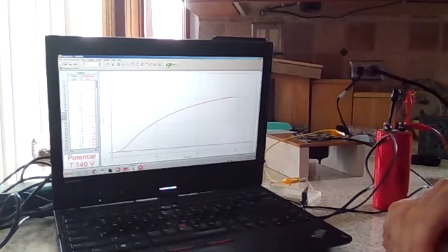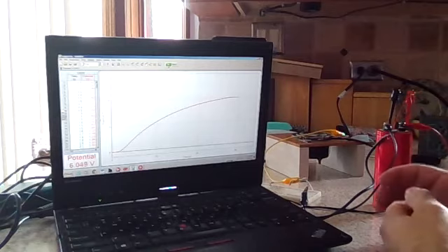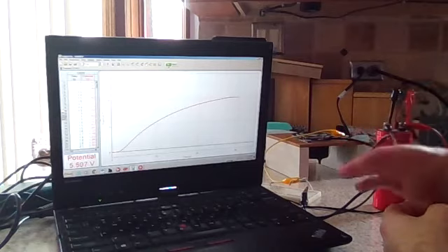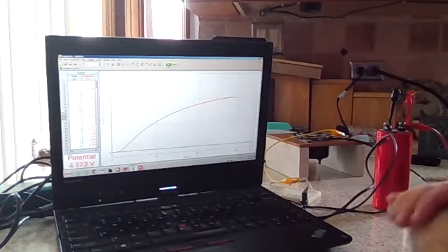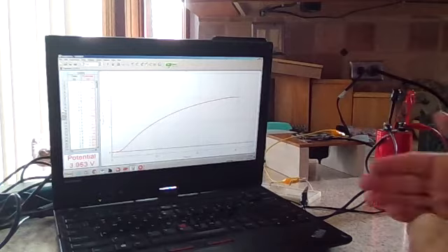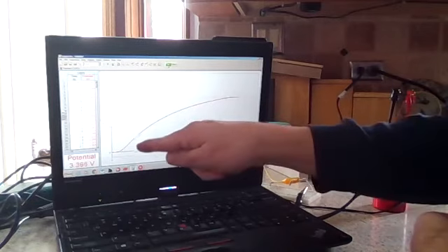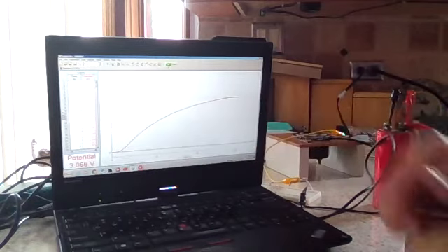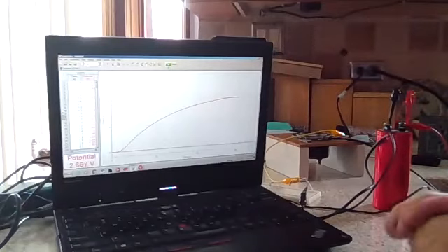That's what we call the time constant of the RC circuit. It's actually the product of the resistance times the capacitance, your ohms times the farads. In this case, I increased the time constant by a factor of 20. Okay, and then it just takes a whole lot longer for things to rise more slowly, to discharge more slowly if we turned off the power.